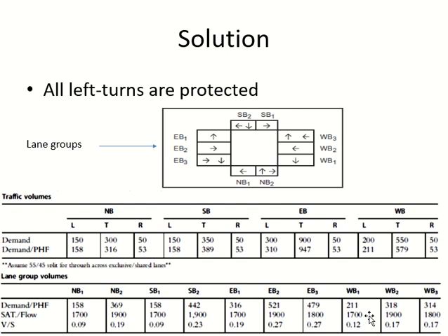After I calculated, remember the peak hour factor? Not plus, divide again. Divide by both. Peak hour factor is 0.9 something, and let's say your factor of heavy vehicle is 0.96. So 150 divided by 0.95 and again divided by 0.96. Clear? So the first thing you do is convert the demand into a passenger cars per hour flow rate: divide by peak hour factor, divide by factor of heavy vehicle, and so on.